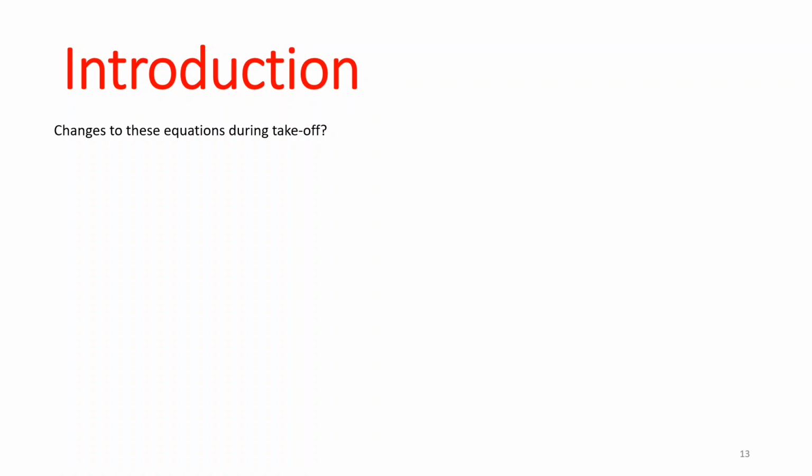But it is so small compared to the exit velocity that you can neglect the inlet drag, the ram drag, because the velocity coming in is so small. Of course, it cannot be zero. It has to have a value, as we have mentioned, but it's so small compared to the exit velocity that you can just neglect it.